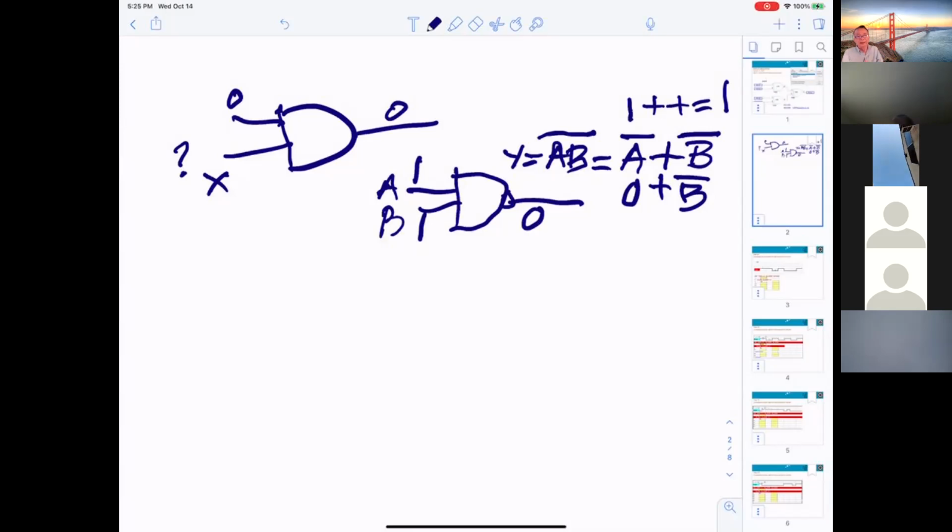The thing is you must understand this. We will be going to the flip-flop. If you don't know how the NAND or the NOR works, it's hard to understand the next one. Okay? So basically for the NAND, if you look back, you must understand: one input 0, output must be 1. However, output will be 0 only when both inputs are 1.